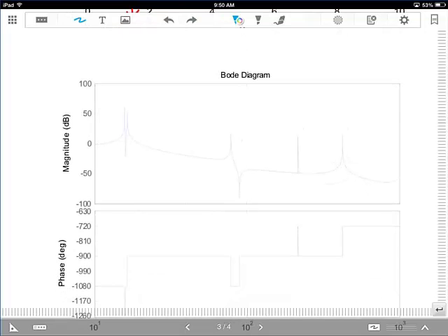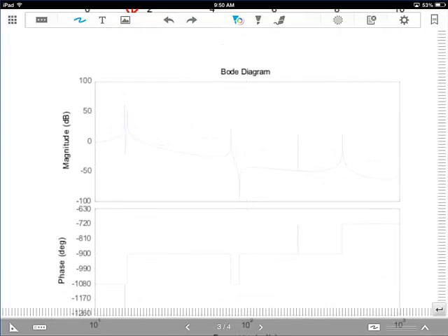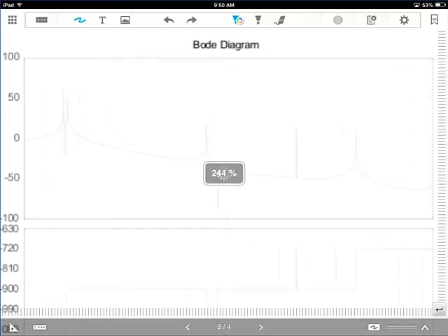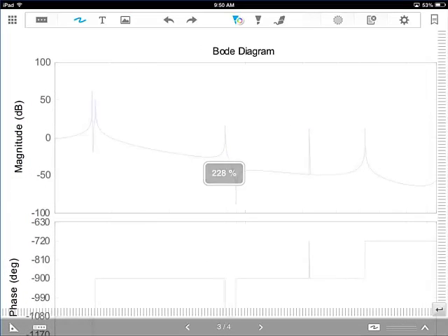And here's the Bode diagram. Now you see a little more complicated stuff going on at those first modes, here are basically omega 1 and omega 2 together. So there's two peaks and a zero, and again, if this was perfect, that zero would cancel the second mode because we're still forcing it at the middle. Now this is what we were looking for with omega 3.